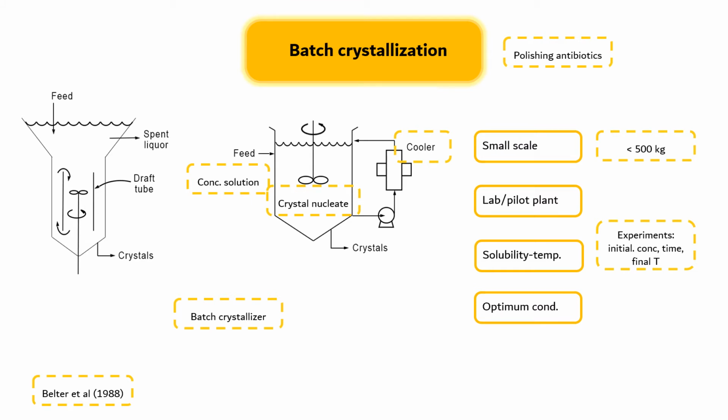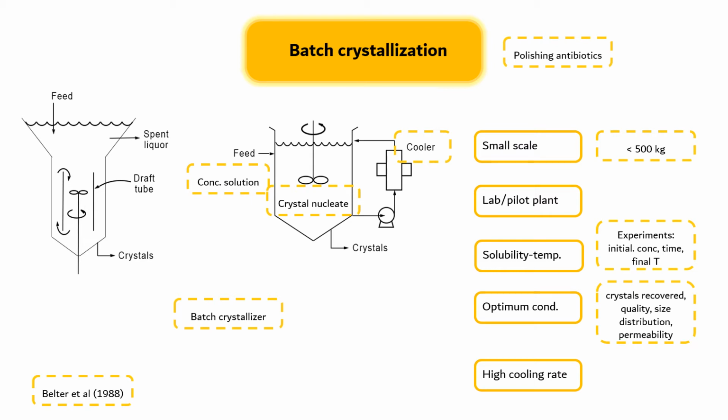One of the disadvantages of batch crystallization is that it often gives a poor quality, non-uniform product. This is due to the high cooling rates at the beginning of the process. These rates result in the formation of excessive nuclei that cannot grow to the desired size. Such overcooling can also cause precipitation on the cooling surfaces, called scaling, which reduces the heat transfer in the crystallizer. These disadvantages can be minimized with proper temperature control, often described as a cooling curve, giving the temperature versus time.